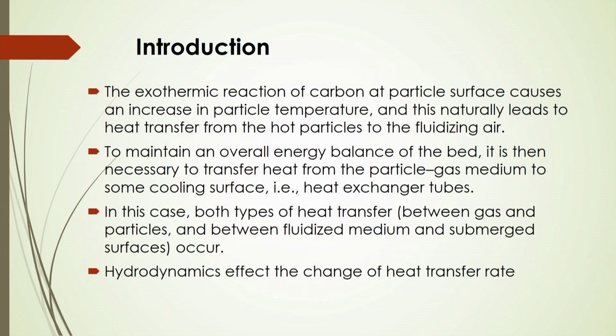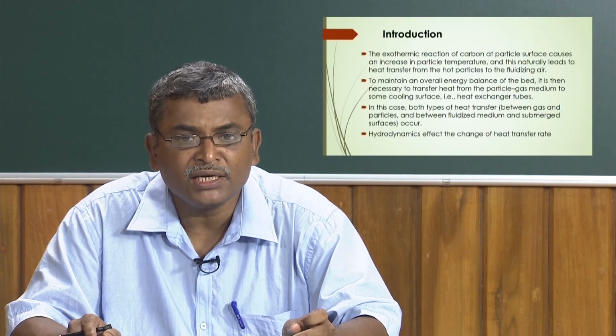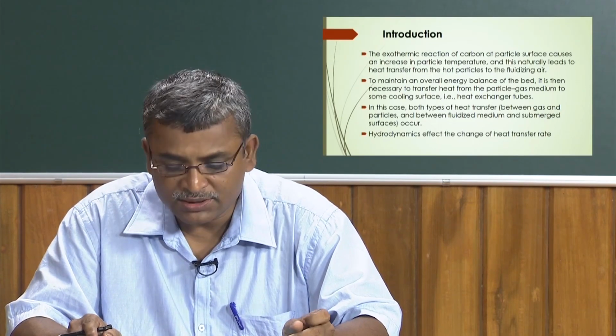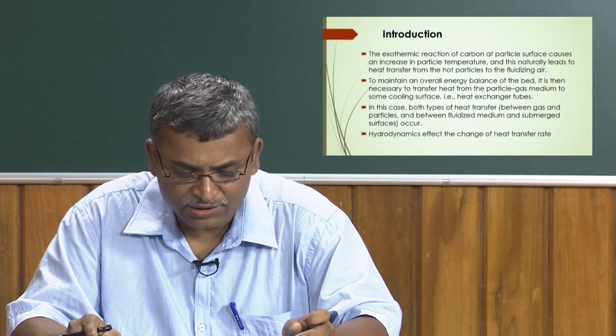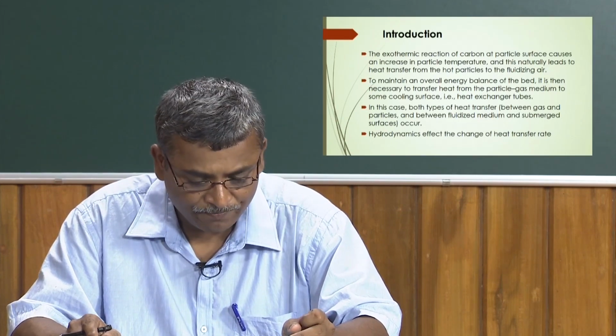Now, where will these heat transfer characteristics be important? Because anyway we are going to study these heat transfer characteristics, this knowledge should be utilized somewhere. So, these heat transfer characteristics are important in this fluidization operation. Now, you know that exothermic reaction of carbon at the particle surface causes an increase in particle temperature, and this necessarily leads to heat transfer from the hot particles to the fluidizing gas.